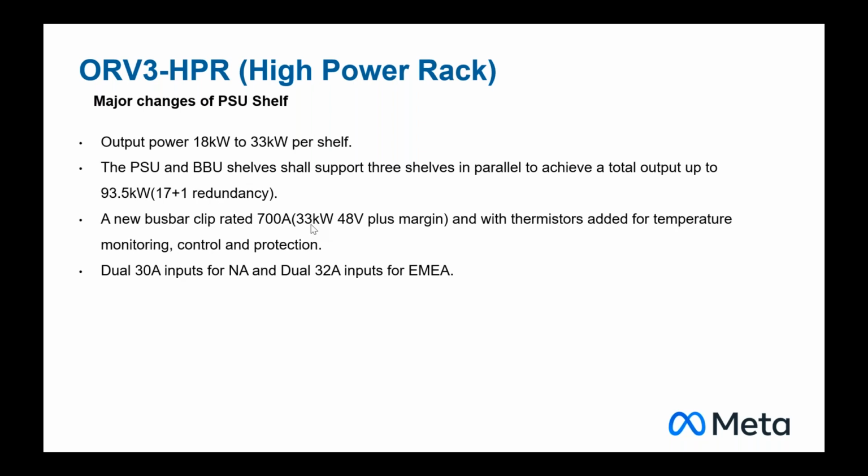It's cheap and reliable. Are you going to use that for information only, or will it be part of safety to trigger over temperature protection? Yeah, the major intention is for safety protection, because in the original design we don't know if the connector is overheating. There's no information on the connector temperature. So if there's a bad contact, then some thermal event may happen. With this thermistor, the last thing we can do is turn off the power shelf by itself if the temperature is over a threshold. We can set multiple levels of protection.